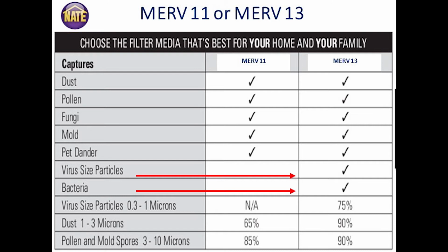I like to use this sort of a comparison. You're putting in a whole home high efficiency air cleaner almost always with equipment change out, new furnace, new air conditioner, new heat pump, whatever it might be. And so you want to make sure that the filter you're putting in has a high enough MERV rating to protect the equipment, to protect that investment. Any of our filters will do that. Then you want a way to separate out MERV 11 from MERV 13, et cetera, et cetera.